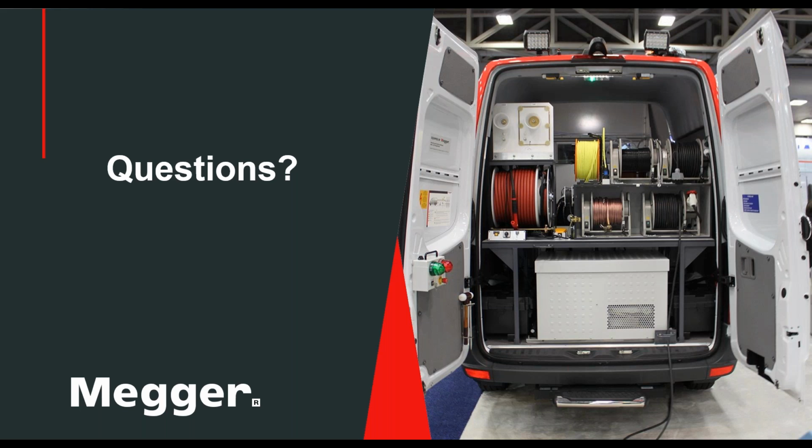So that's why you might need more joules and more voltage to get the initial flash over and to maintain the arc when you do the arc reflection method. There's also another method that we didn't talk about today. It's the surge pulse method, which is a very well-known and long-proven method, which might be on paper cables a little easier to use if the arc reflection does not work.